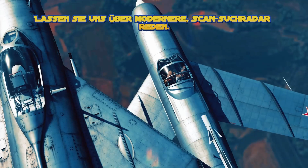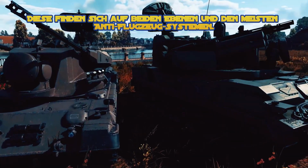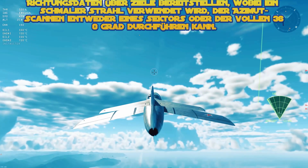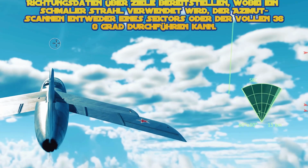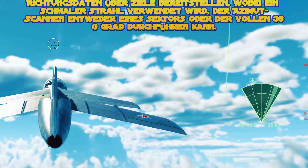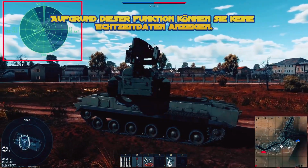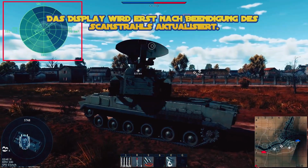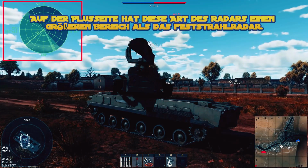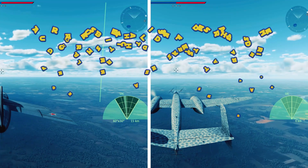Now let's talk about more modern scanning search radar. These can be found on both planes and most anti-aircraft systems. This radar can provide both distance and direction data about targets, employing a narrow beam that can perform azimuth scanning of either a sector or the full 360 degrees. Due to this feature, it can't show real-time data. The display is only updated after the scanning beam finishes its sweep. On the plus side, this type of radar has a larger range than fixed beam radar.